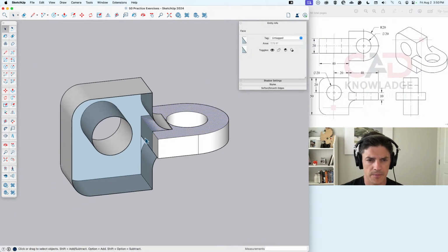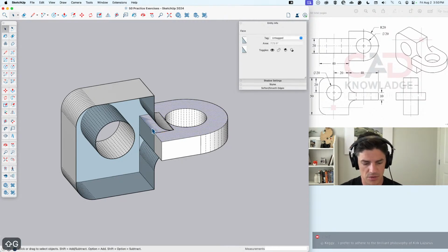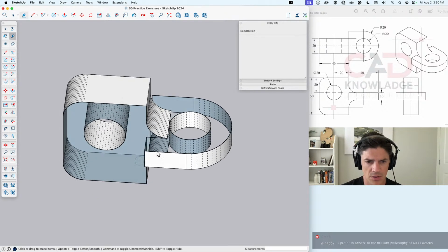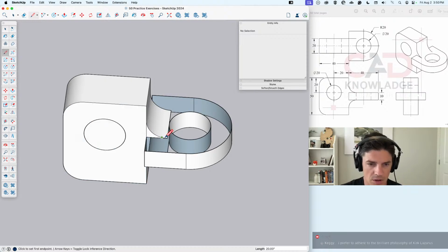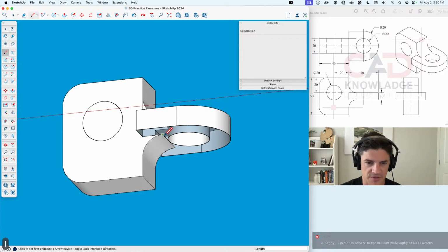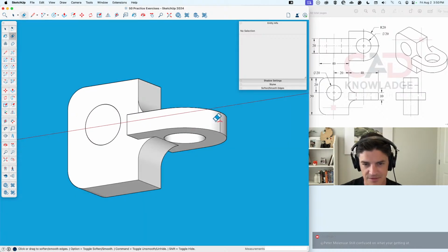You have Z-fighting on that one, so you've got a double plane for some reason. But shouldn't it be merged? Should be. If you take that out, you're going to lose your face. What happens if you try to close that, if you heal it? Because if it's not flush, then it's not going to heal. There it is. Everything's flush. It's all tens, all the way down. Okay. Well, it just didn't like the order that it was drawn in then.